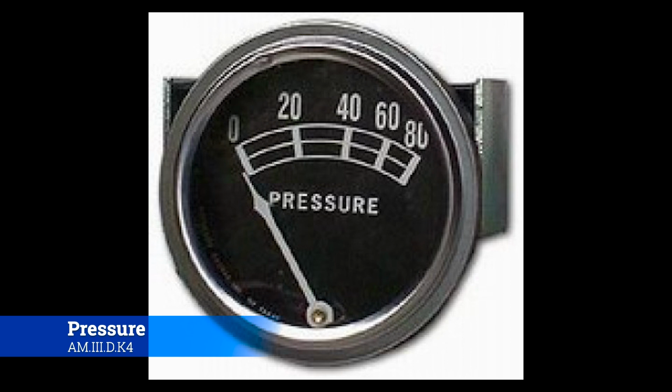If there's a lot of oil in there, the pressure is super high. But as it starts to fall off, the oil pressure goes with it. And then, as we discussed earlier, as there's less oil in there, more heat can be concentrated per unit of oil. So therefore, the oil is going to come up in oil temperature. Those two are almost inversely related.